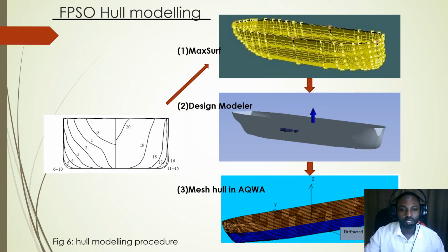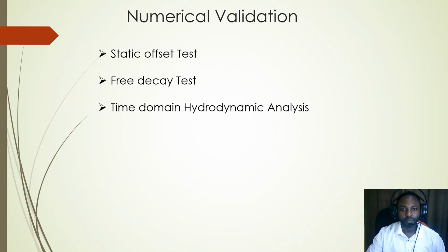So for the FPSO hull modeling, in the reference paper, the midsection of the FPSO is given, which was imported into Maxsurf and modeled, then exported to Design Modeler for modification, and then to ANSYS Aqwa for meshing and further analysis.